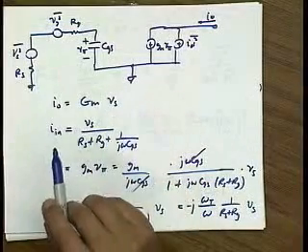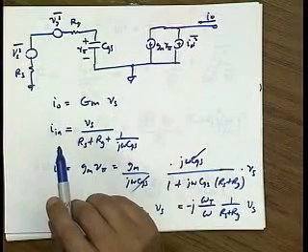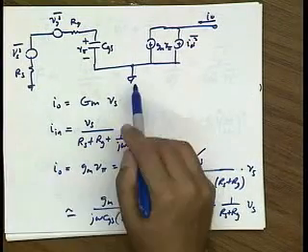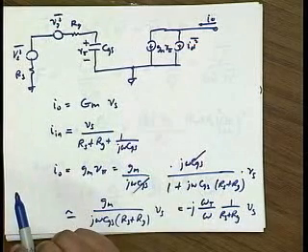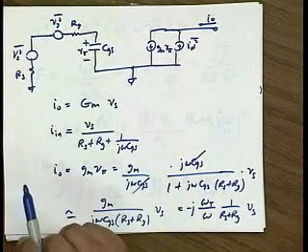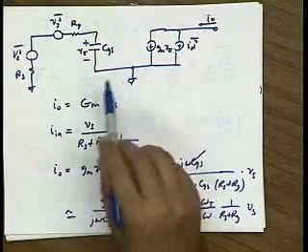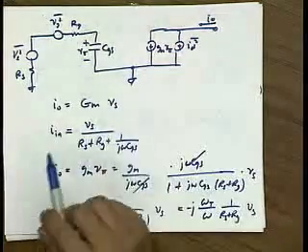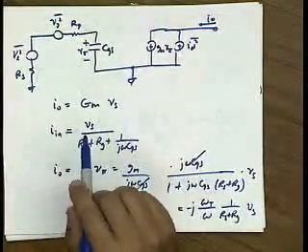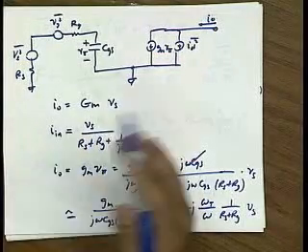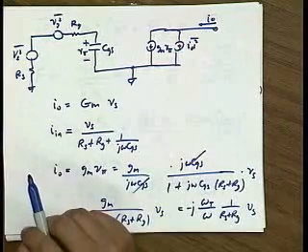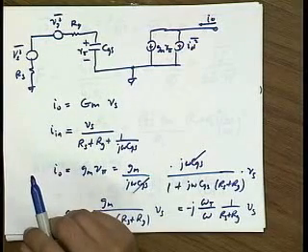Anything else that we've neglected? Source resistance? Oh, you mean the resistance down here? Yeah, that's true. We have neglected that, and that may be important in certain applications. Usually we like the device to be fairly big for the LNA, so the source resistance won't be too large, but certainly something that we could include in the calculation. Good midterm problem.